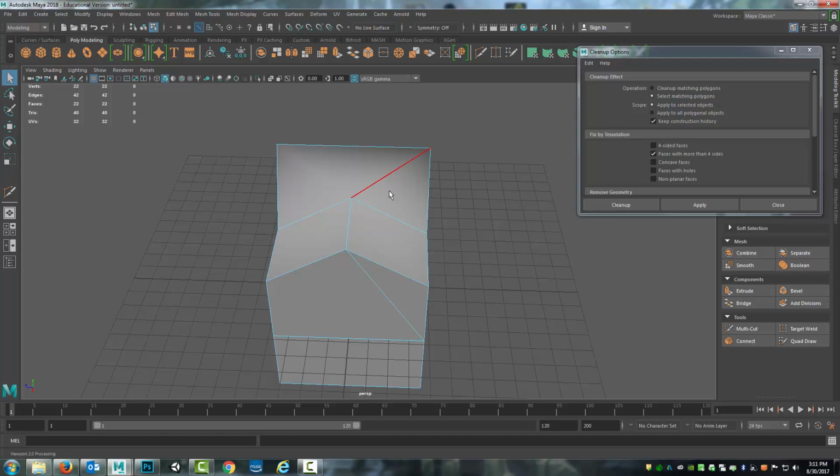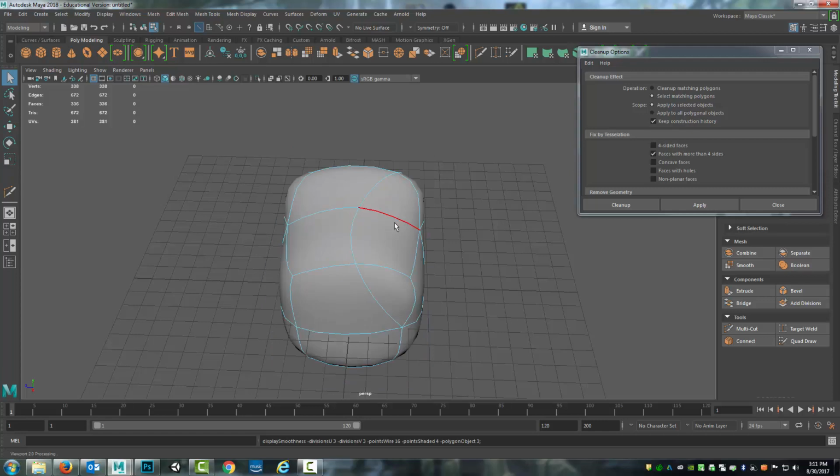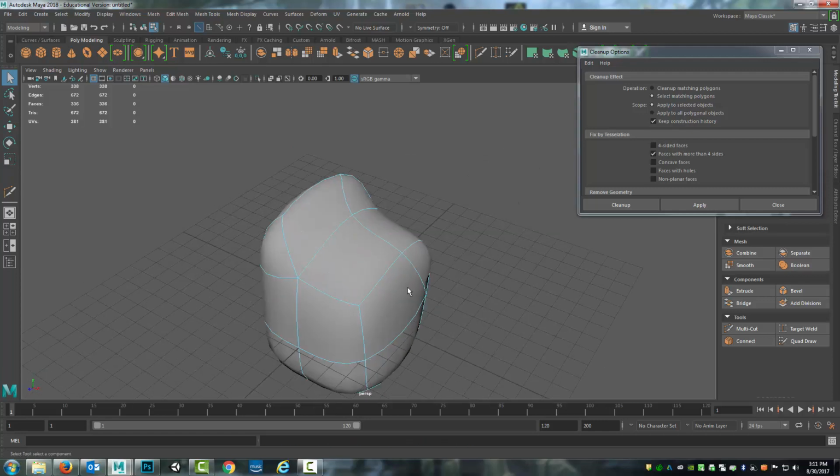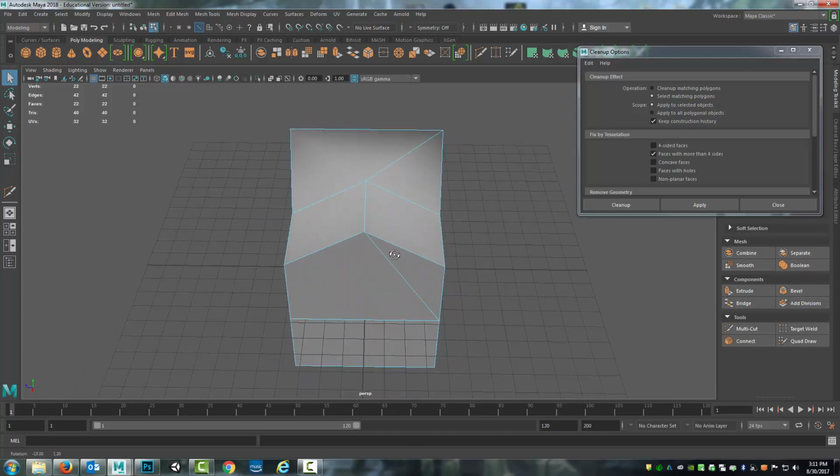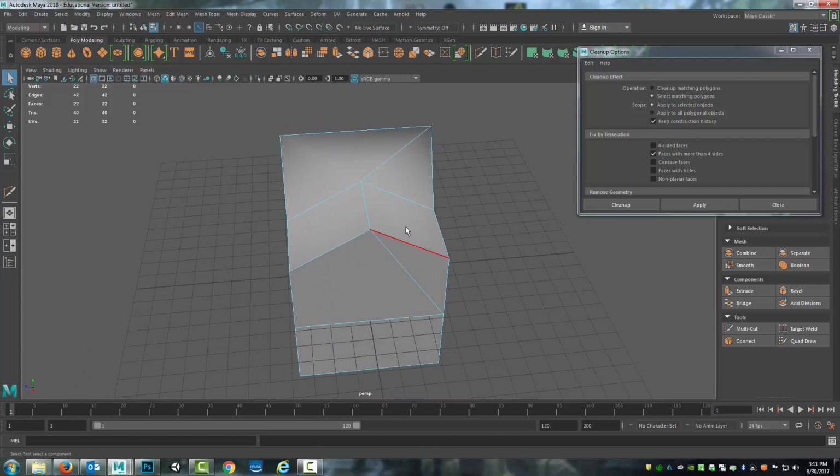When I was working on some DS titles, yeah, everything needed to be triangles. We had to pay very close attention to how high the geometry count was, and we were worried about triangles, not quads. But as we've advanced to a point where we can do very high resolution sculpting, when we can do things like these sub-D surfaces, it's more important to actually keep everything in quads so that you can very quickly and efficiently add in new edge loops and create new forms and make adjustments and changes on the fly.